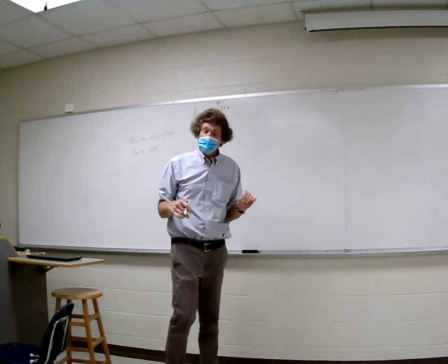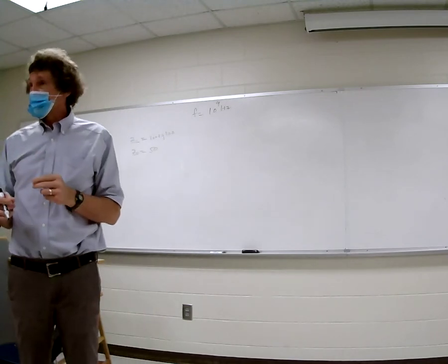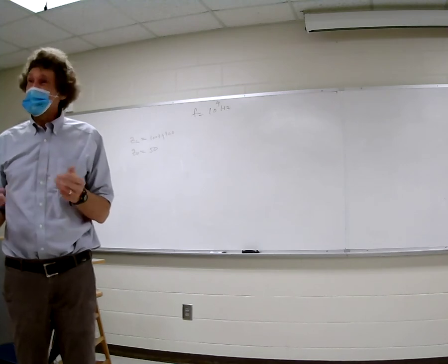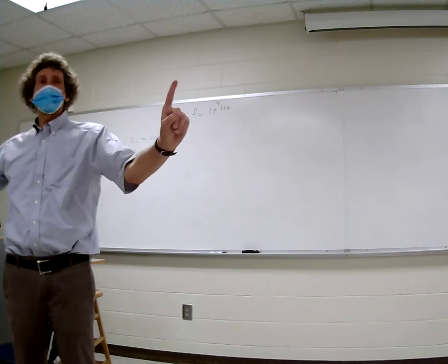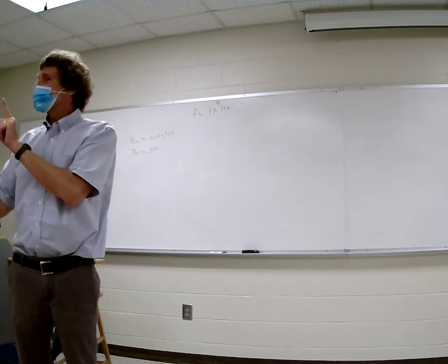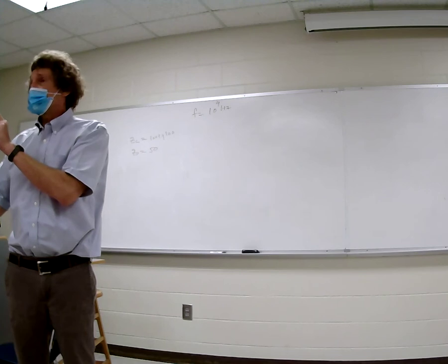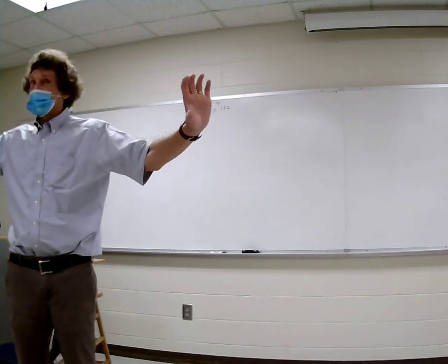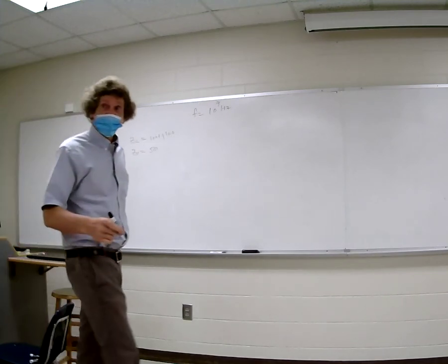So we know that the wavelength there is 30 centimeters, right? c over f, c is 3 times 10 to the 8th over f, which is 10 to the 9th. That's 3 times 10 to the minus 1, or 0.3, or 30 centimeters, right? A meter is that long, 30 centimeters is about that long. That seems fairly long for a printed circuit board, so you don't have to worry. But when you get into larger electronics and you're going from power supply to antenna, probably everything goes into the domain where you'd better impedance match. Y'all follow me on this?